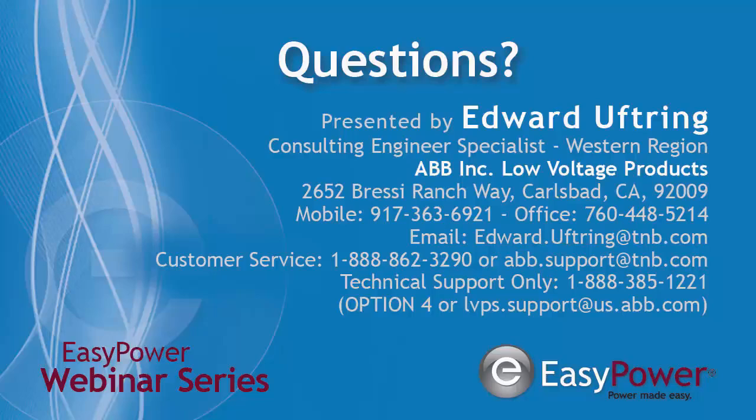What happens with a current higher than the nominal maximum current? Can the load be safe anyway after the breaker is damaged or destroyed? Yes, it can. So if you're going over the nominal maximum current, what we foresee is that our breaker is going to absorb the biggest punch and be damaged. Not the safest. You may smell fire or see smoke coming out of the panel. Nobody wants that. But typically, your load down the line is going to be safe from any damage getting to it.